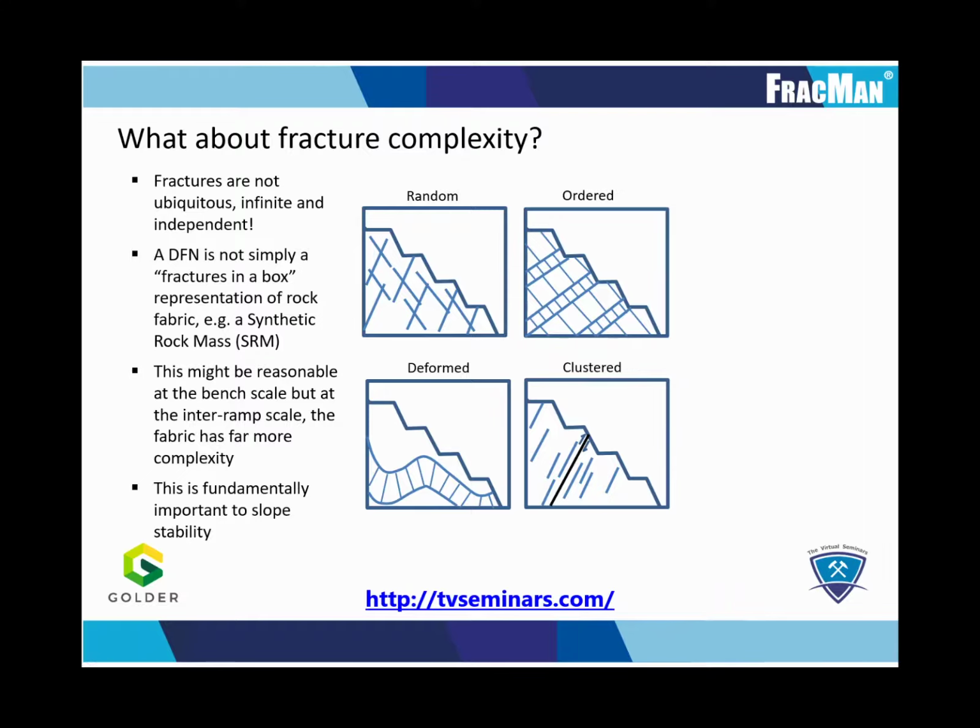This might be reasonable for bench scale analysis, but representing the structural geology and its complexity becomes very important to slope stability at the interramp scale. Some simple conceptual arrangements of fractures might be randomly organized, they might be deformed, they might be ordered and arranged into more regular layered systems, or they may be clustered around major structures, or a combination of several of those. Capturing this in the model is very important.